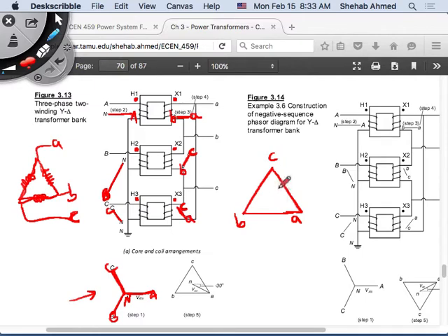So this is my phasor diagram for the voltages on the windings on the secondary side. What did we want to do? What we want to do is take this and convert it to a single phase equivalent circuit, so it's like taking this delta and connecting a star across it, and seeing what's the phase voltage across the corresponding star that will be placed across this delta of the transformer.